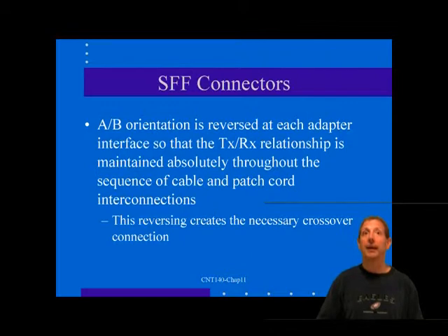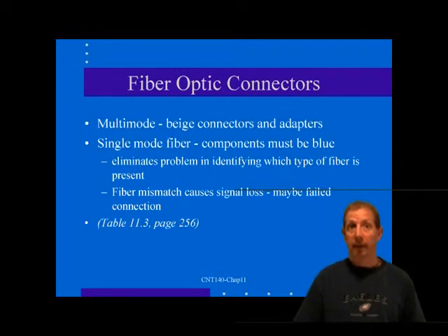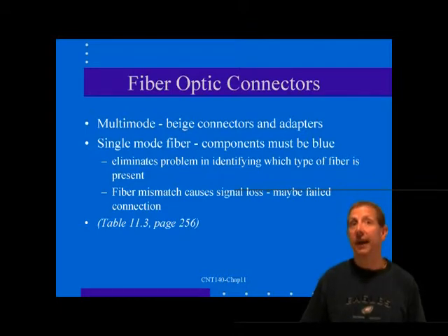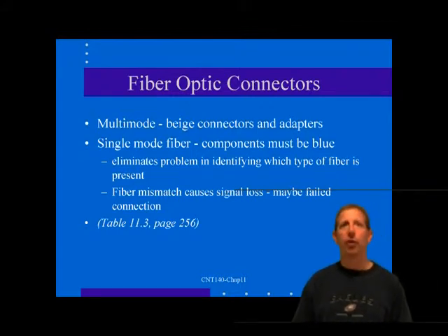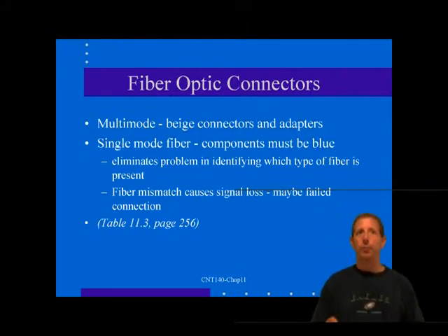Next, we want to talk about connector codes. The TIA 568C.3 requires a different color for connectors and adapters according to the fiber mode. Multi-mode components are required to be beige, while single-mode components are required to be blue.